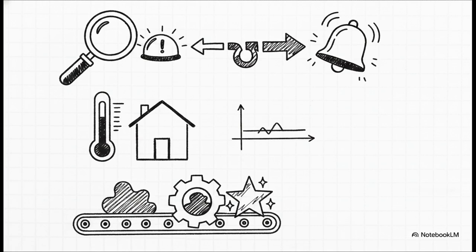Next up in the recap, architectural patterns. There are 3 essential patterns commonly used in embedded real-time systems design that you have got to know. First, observe and react. This is typically used in monitoring and alarm systems, where sensors are checked and actions are taken if certain conditions are met. Second, environmental control. This is for systems that manage and regulate physical environments. And third, process pipeline. We use this in data acquisition systems, where data flows through a sequence of transformations, like a raw sensor reading being converted, then processed, and finally displayed.